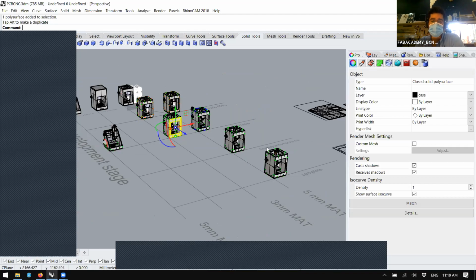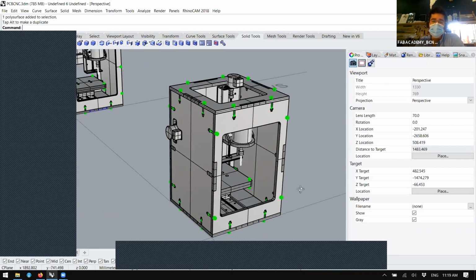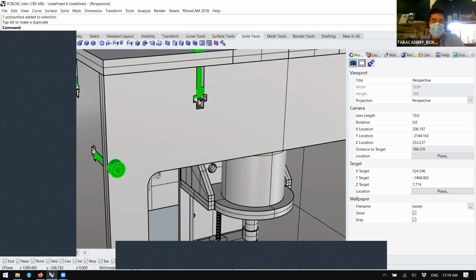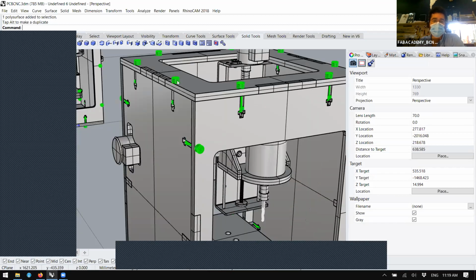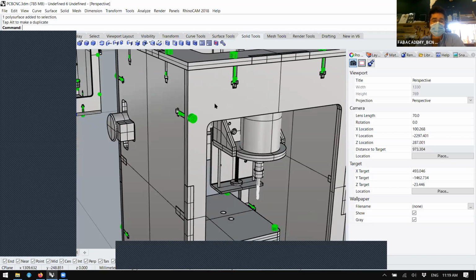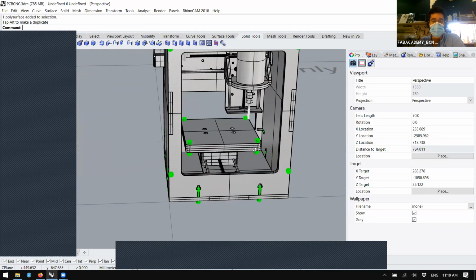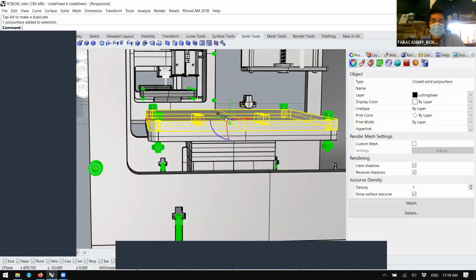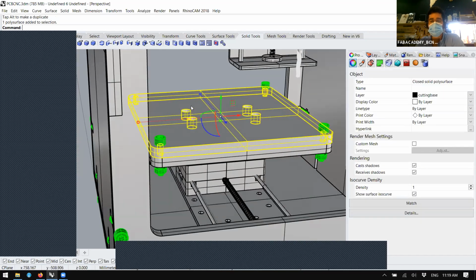Once you get to this design, for example, you start fixing things. And this is, for example, the final thoughts on the screws. For example, there is a minor difference in the length of where the nut fits into this piece of acrylic. You want to have it as deep as possible, but not too deep, because not only does it look ugly, but you will need longer screws. But if this nut holder is too close to the acrylic, it is going to support a lot of stress. So you want to have a bigger area to dissipate the stress of the screws on the machine. And some minor tweaks, for example, thinking of the Z plate and how you're going to mount it.